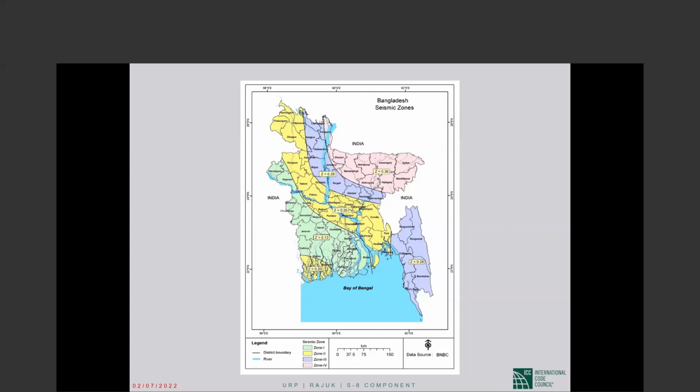It is in a different range of earthquake. So depending upon the earthquake, it may become more critical for the building or may become less critical. You see what I'm saying? Depending upon the predominant period of the earthquake, the lengthening of the period of the building may put it in the critical range or may take it out of the critical range. So what would happen, you do not know.